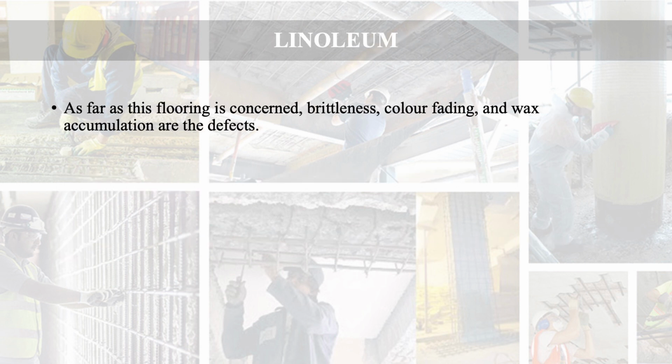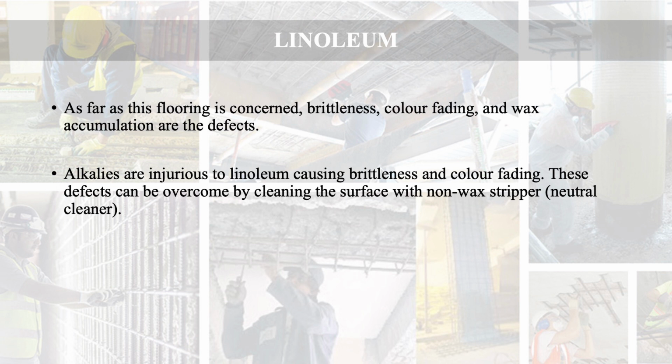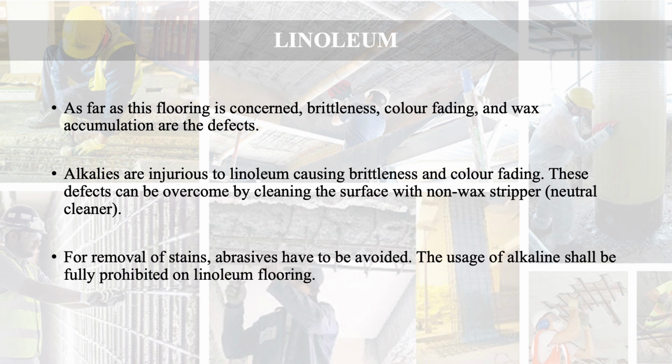Now, linoleum flooring. As far as this flooring is concerned, brittleness, color fading and wax accumulation are the defects. Alkalis are injurious to linoleum, causing brittleness and color fading. These defects can be overcome by cleaning the surface with non-wax stripper, that is neutral cleaner. For removal of stains, abrasives have to be avoided. The usage of alkaline shall be fully prohibited on linoleum flooring.